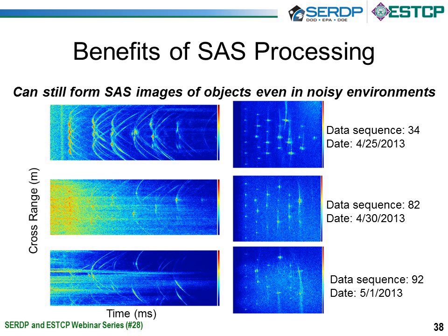And you can see that particularly for the middle image on the left-hand column, where you can barely see the front row of targets, whereas on the right-hand side, after beamforming, you can see the front row of targets very easily, and in fact we have a very large SNR. And again, the point of these low-frequency images is not to generate a beautiful picture, but to show regions of interest where we are interested in seeing, hey, there's an object here, is this a UXO or not a UXO, and then extract those spectral features. And in that spectral feature domain is where we're going to find the discriminatory features that allow us to determine if it's a UXO or a non-UXO.